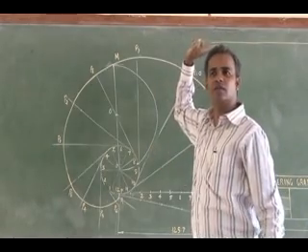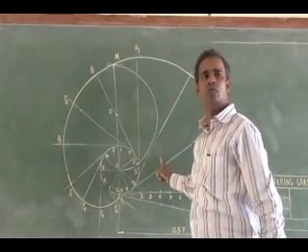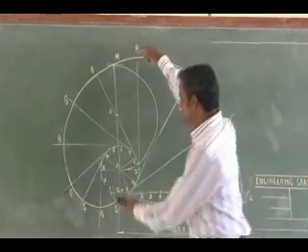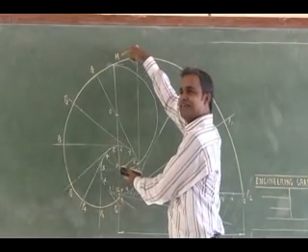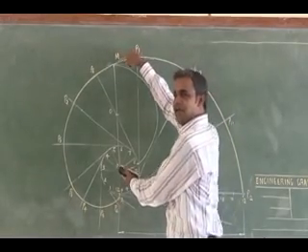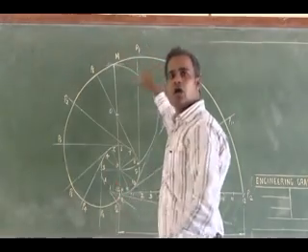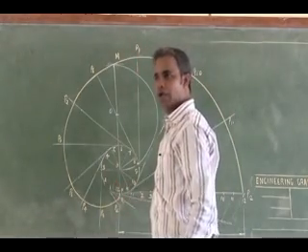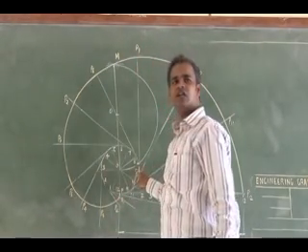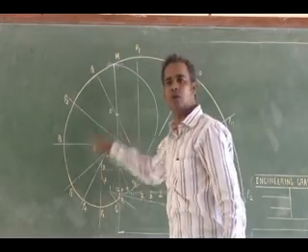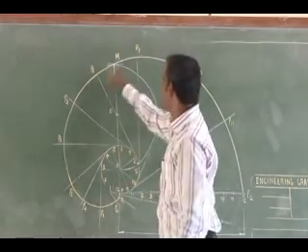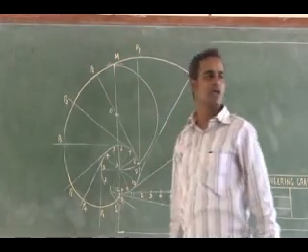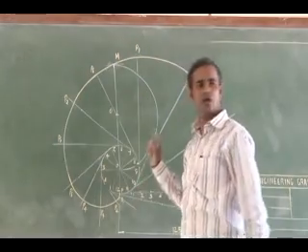For polygon, the procedure is simple. Here you have to mark the point first of all. Then center to that point, what is the length? Using that as diameter, draw a semicircle along the direction of the involute. That semicircle will give you an intersection location on the original circle in between the same segments where you have the point.